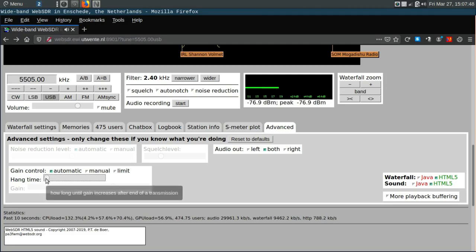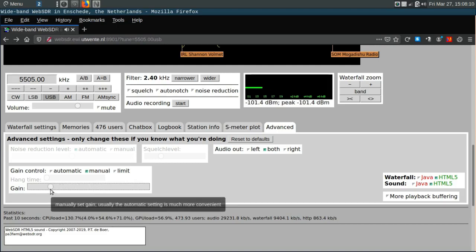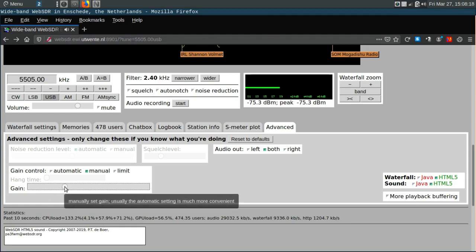We can't directly keep the AGC and set a particular gain setting as the default, but another thing we can do is turn off the automatic gain and go manual. When we go manual, we have to manually adjust this down to a lower gain setting. It is possible to adjust the gain to so low a setting that you cannot hear anything.